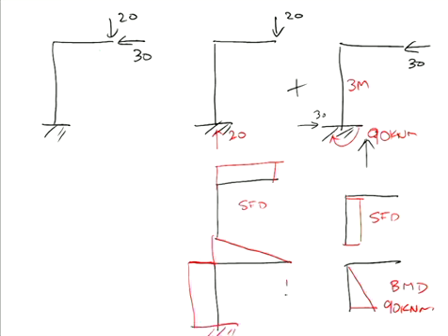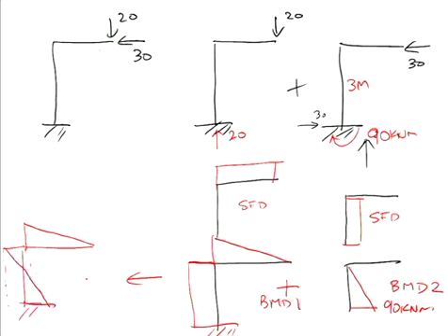So when you look at the bending moment we got on the other page, it was a sum of bending moment diagram 1 and bending moment diagram 2. So if I add them up, I come up like so, going around the corner, one is constant and one is reducing, so that will give me that combined bending moment diagram that we got before. Okay? So, look at this in your own time.